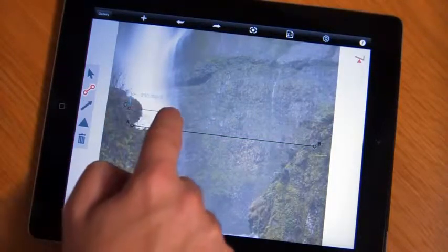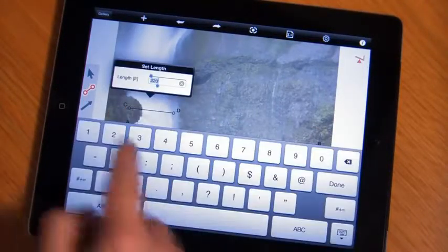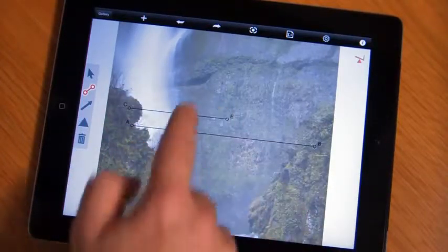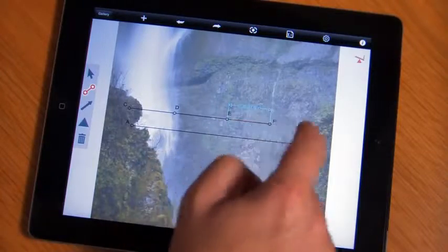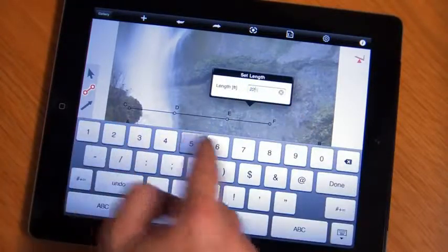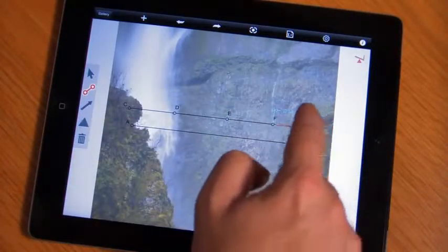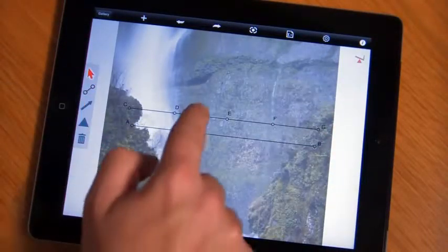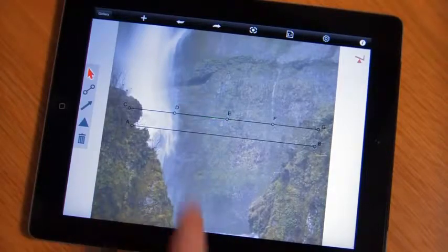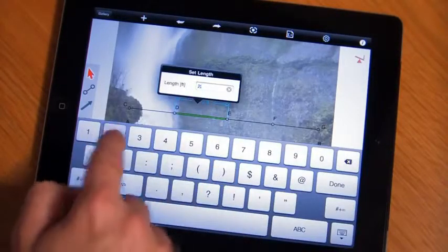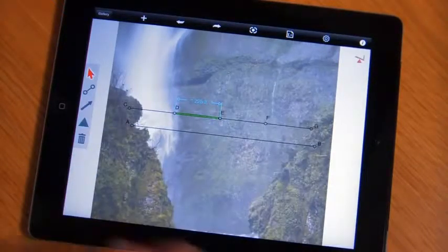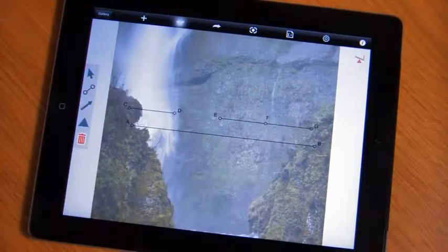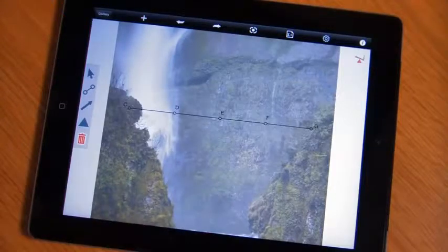So now I can draw the individual segments for the bottom of the bridge. We'll set all these at 225 feet, and we'll start with a design that has 4 of them. And we can go from there. I think we missed one, so we can go back in and reset the distance on this one by just clicking on the dimensions, setting it to 225. And now we'll go ahead and undo that, and we'll remove our reference line.